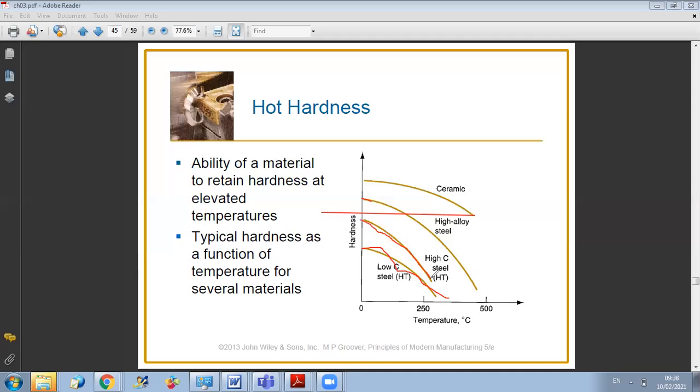So this is the curve for high carbon steel, and also we have much alloys of steel. And by implementing other components to steel, you can reach a much higher hardness. Okay, so this is the importance of creating alloys or of combining several materials together, because you can play with the properties in this way. So if you desire to have a higher hardness, you can prepare alloys that will give you better properties. Or if you increase the percentage of carbon, it can also increase the hardness of steel. So always you should know what is the property desired to know what are the strategies to do.